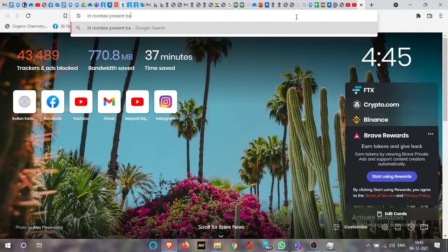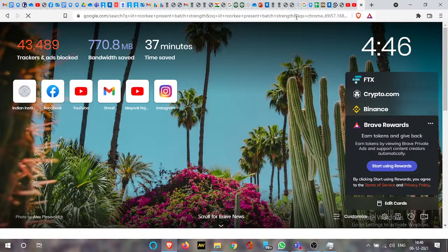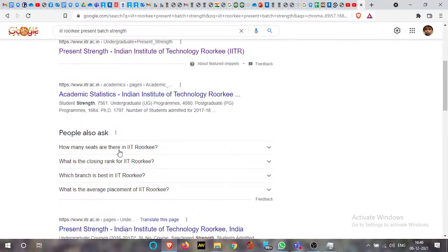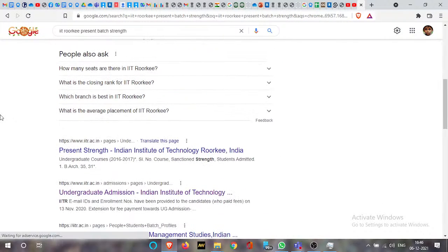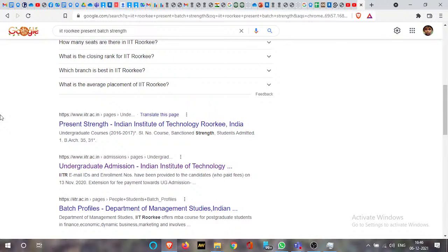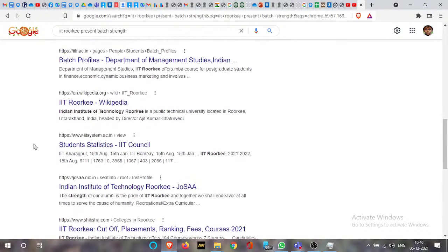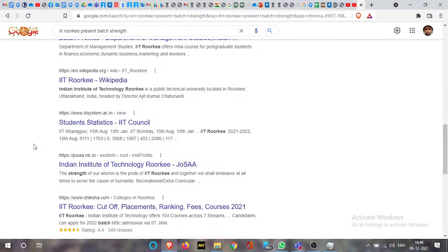Now I am emphasizing so much on this magnetoresistance part, and why am I emphasizing on this magnetoresistance part? Why is this magnetoresistance so important? Because you see, this magnetoresistance response basically gives you a sensing capability. So if your magnetoresistance response is very high, it means that you have two states: high resistance state and low resistance state. And the larger the magnetoresistive response, the better will be the sensing capability.